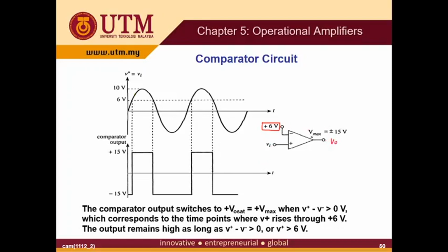It is stated here the maximum voltage is plus minus 15 volt. So the maximum is plus 15, the minimum is minus 15. Okay. Consider this is your input. Your input is a sine wave with the amplitude of 10 volt. So how can you draw the output waveform?